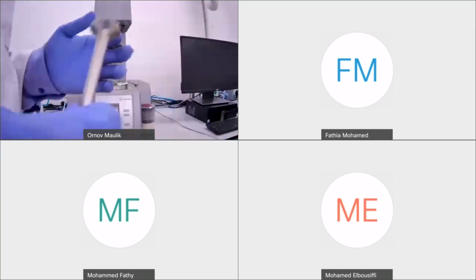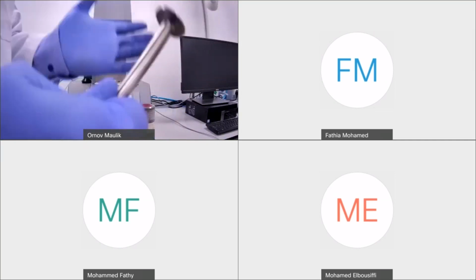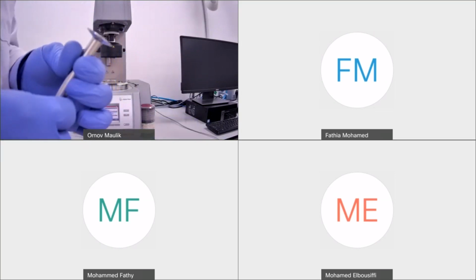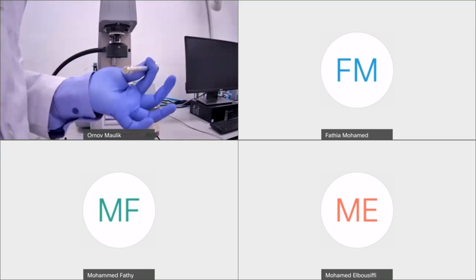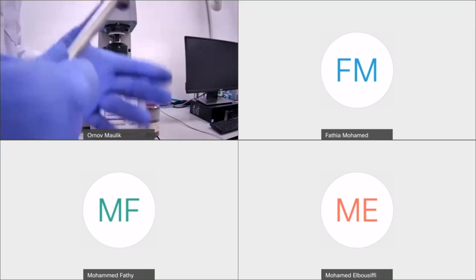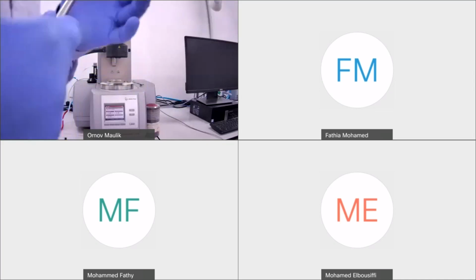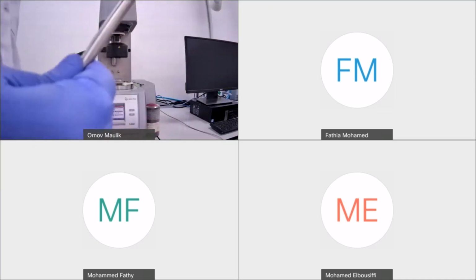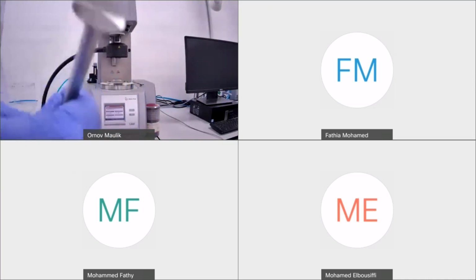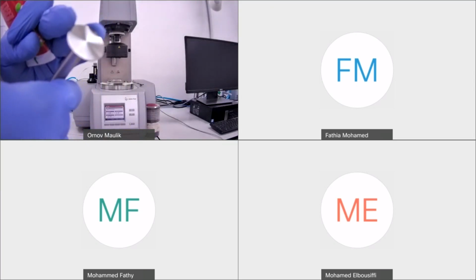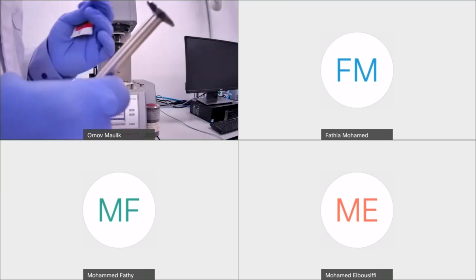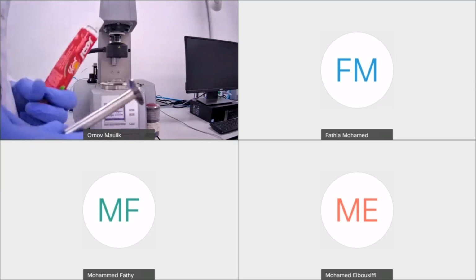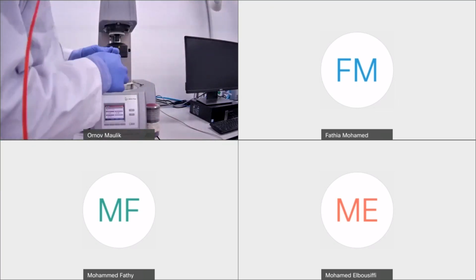You have a minimum and maximum limit of torque measurement, and to compensate for that, the stiffer the sample, the smaller the geometry dimension. This can be a thumb rule for deciding which geometry to use for what type of sample. Here I am measuring a viscoelastic solid, so even with a lower dimension geometry, sufficient torque would be generated at the motor system. I'll put this geometry onto the air bearing coupler.